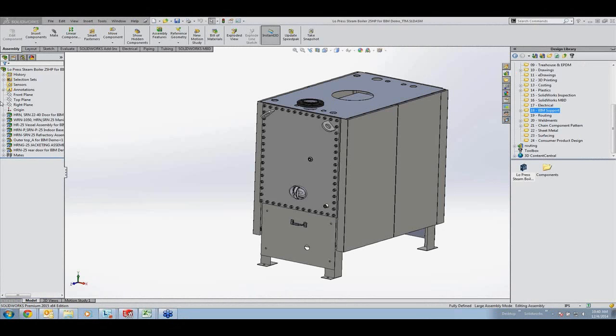So first of all, I'm going to select my mounting location here and a reference point. And then I get to choose how much detail I want to show up in that AEC file. So here I'm going to choose custom, and then I get to choose which ones I want to hide. In this case, I want to hide my fasteners. It's not necessary information for architectural software.